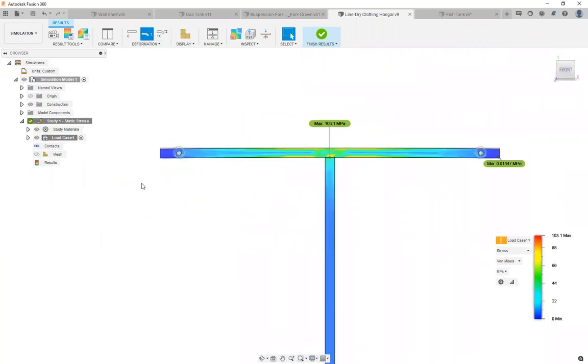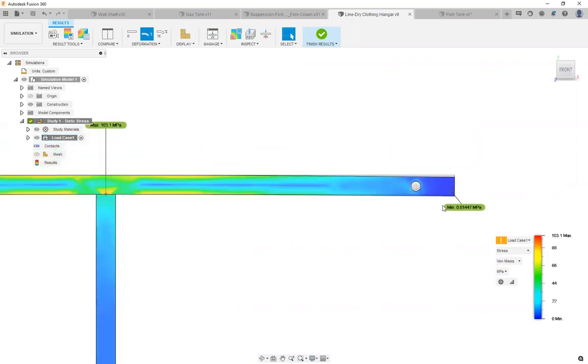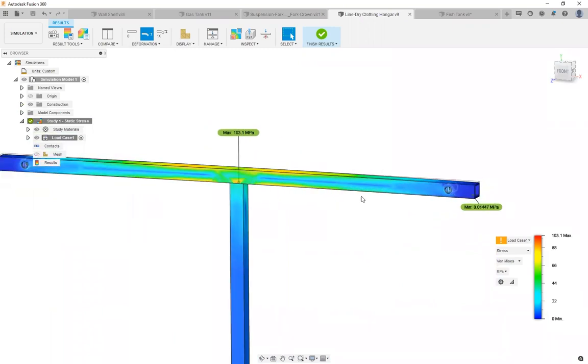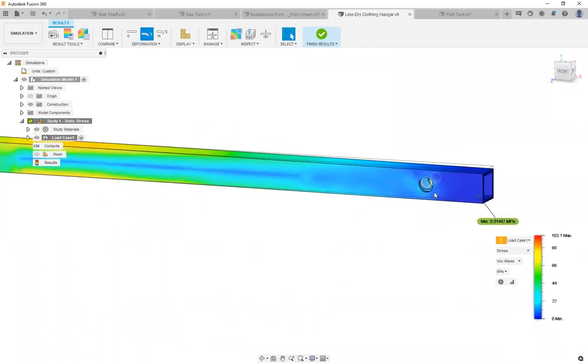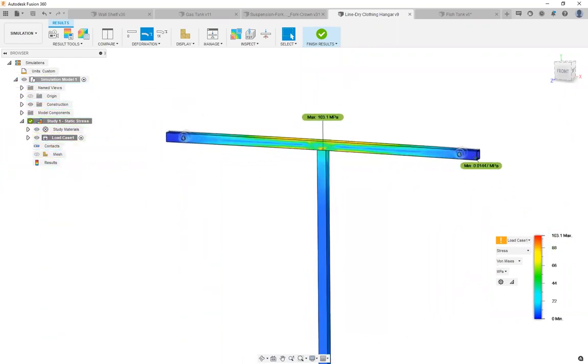And this is the actual deformation of the model, which is this middle guy here. And you can see this representation of how little it dropped. It is going down a little bit because it's bending a little bit, but it's not by much. So that's when I would apply a bearing load, is whenever there's a cylindrical face, and then there's gravity that's helping with the force of it, or it's being hung onto this, like some wires, for example. All right, let's go ahead and hop over to remote force or moment.